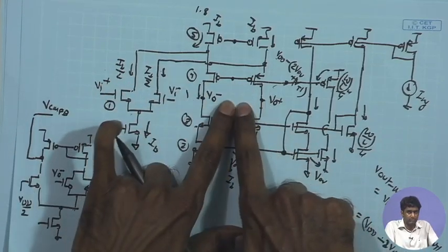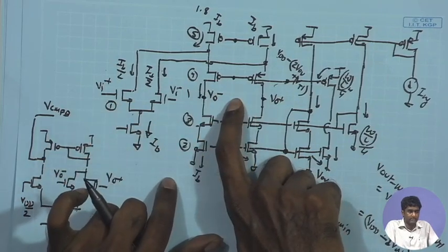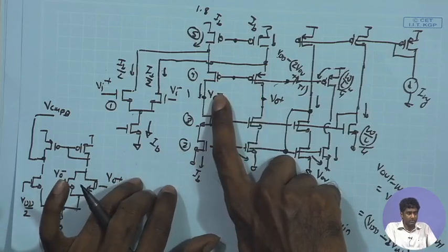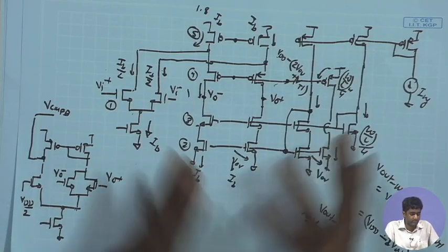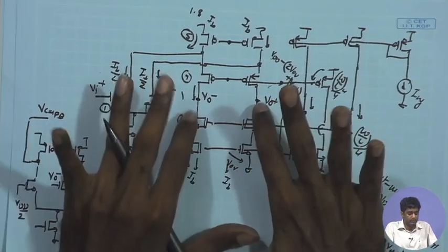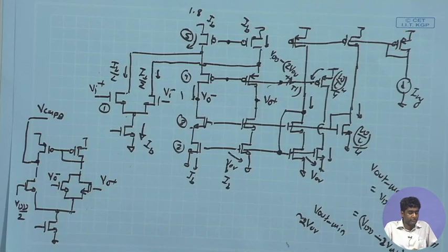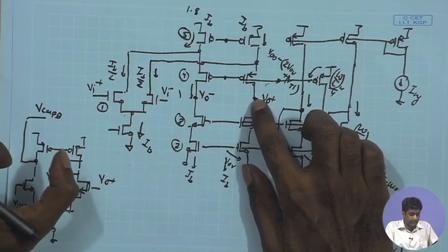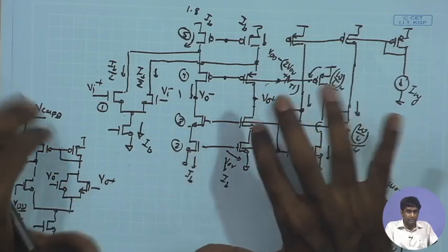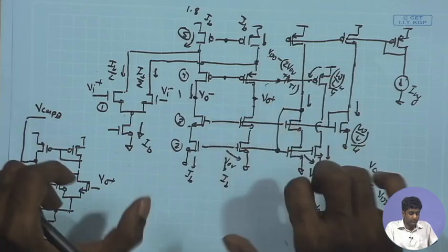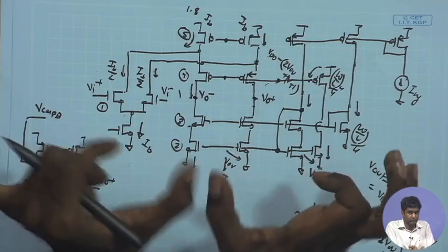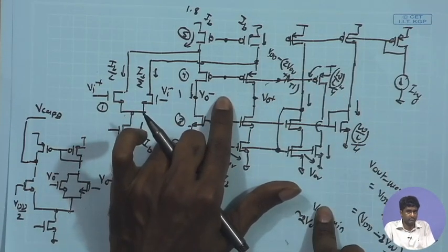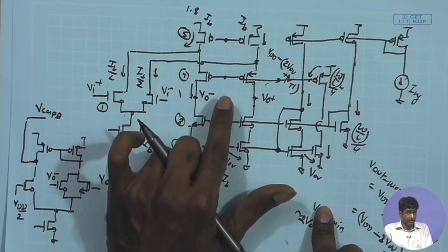But when you are doing the common mode feedback, the common mode has to be extracted faithfully, so these two resistors have to be matched. Passive resistors you can match using appropriate layout techniques that we will be discussing in subsequent classes, maybe today also we can discuss briefly. So that can be well matched, but if these resistors are implemented using MOSFETs operating in the deep subthreshold regime, the two resistors you are trying to construct can have very drastic mismatch, and that will not allow you to extract the common mode potential faithfully, hence it is not a suitable technique.